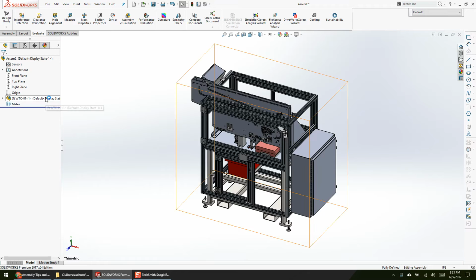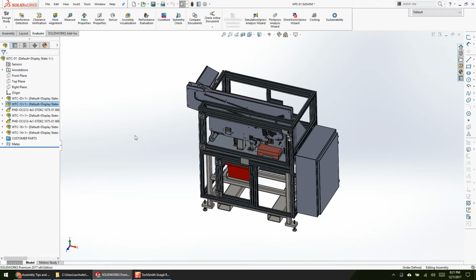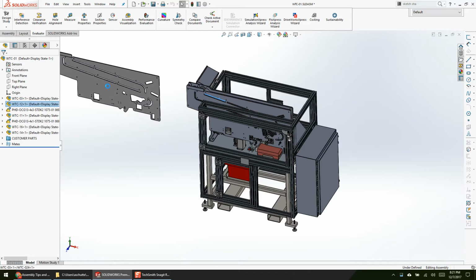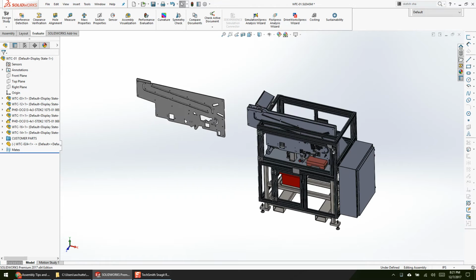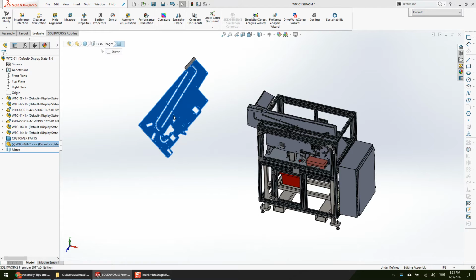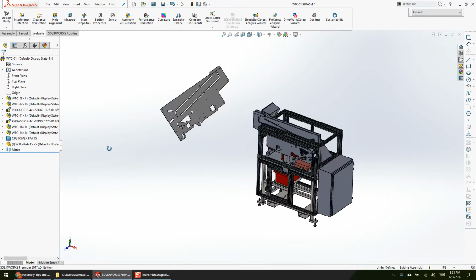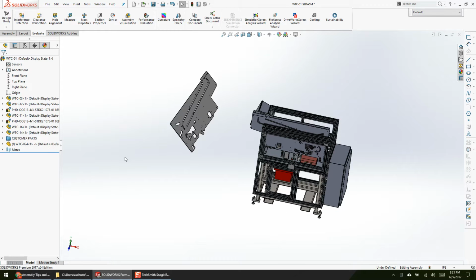Because everybody knows what assume does. So if you do the green check mark, what point on the component is it fixing to the origin? Nothing is fixed to the origin. It's fixed in random space. I thought you just said the green check mark fixes it to the origin. It places it on the origin and fixes it. It puts it in geometric space. It does not constrain anything. Not coinciding. So it's like this. I can rotate this in random space, right-click, fix. This is now fixed. It does not move, but it's in total random space. If you click the green checkbox, it just happens to be in total random space on the origin. But no particular point on the origin, just wherever it landed.